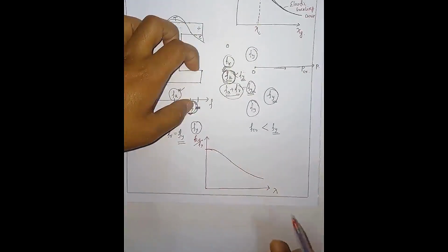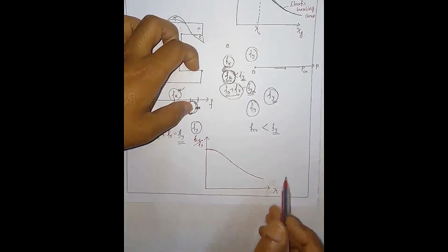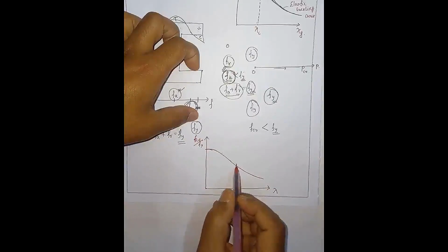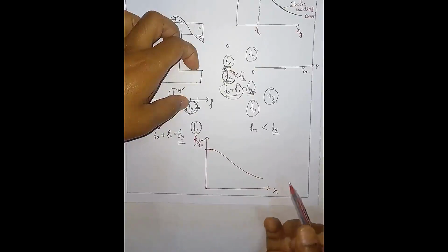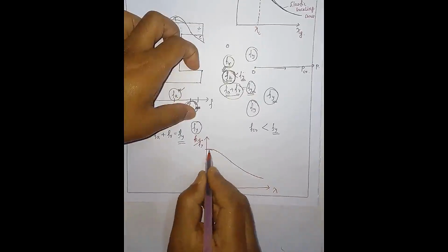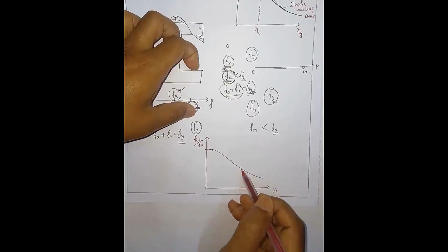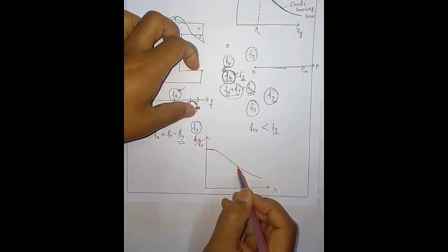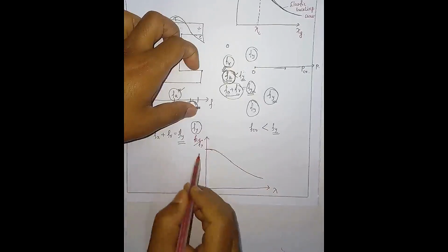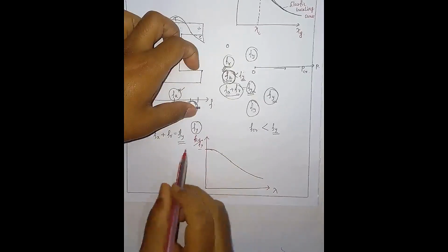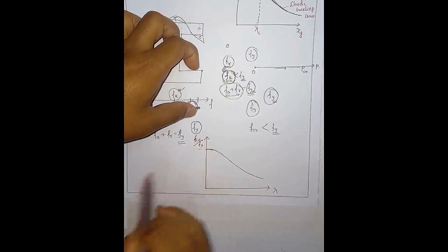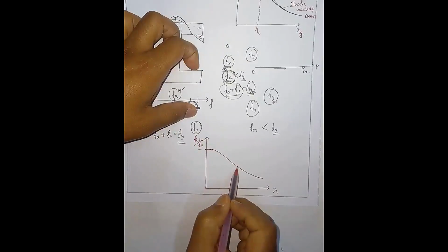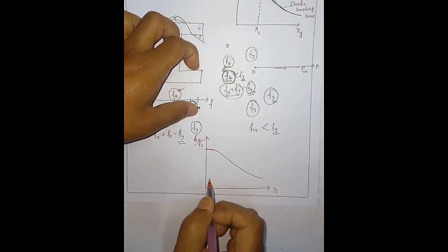If we add all the effects, because in actual practice we never get the desired strength of the ideal case, this is actually a buckling curve for a column, from which we can find the strength, the load carrying capacity or stress carrying capacity, that is fcd. This buckling curve will be different for different classes of sections.